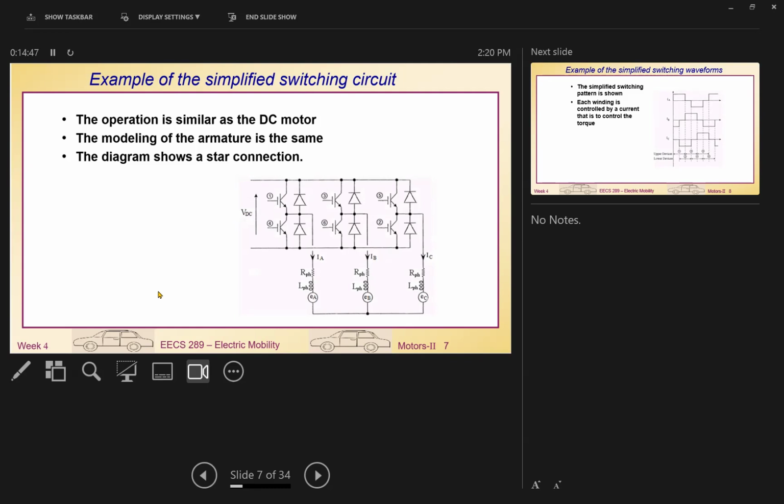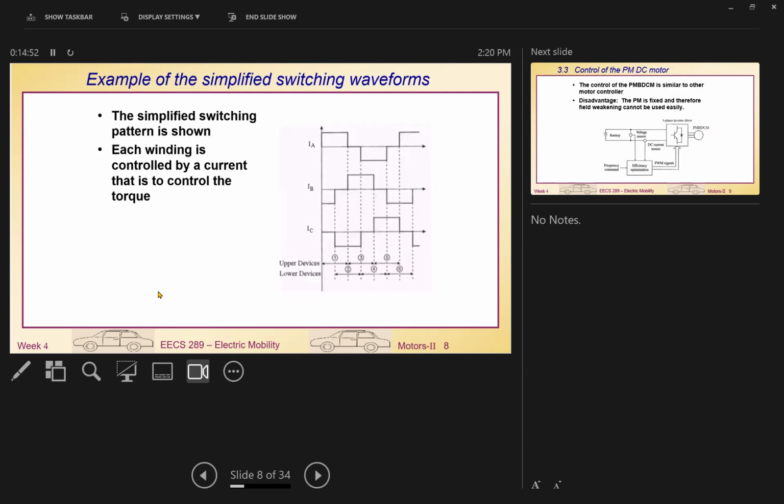So this one will show you a star connection. And it's getting complicated now, but I just show you the waveform. I will not examine you about this, but just show you the waveform like that. So what we try to do with it, you see we have a three-phase IGBT inverter system. You turn on some particular phase to make the waveform become a kind of square wave, but not exactly a square wave, a closely square wave. Sometimes you turn off, it becomes 0 volt.